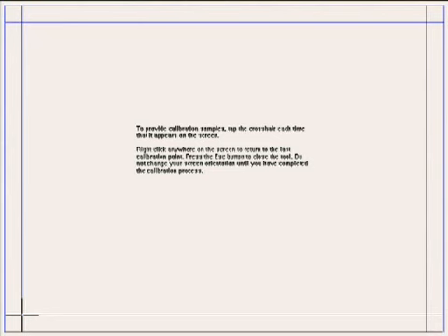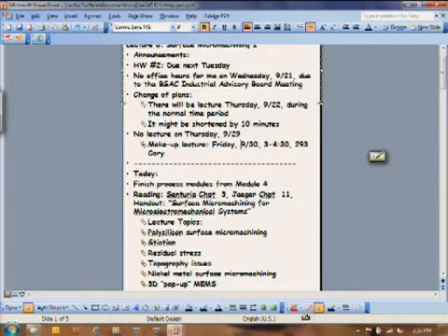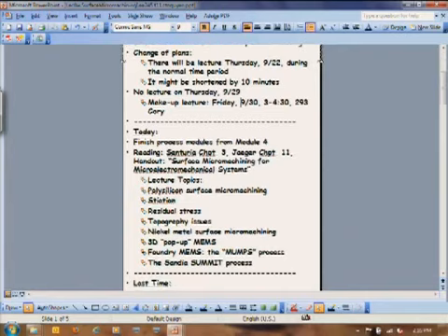Okay, so we'll talk about surface micromachining in general, just the whole process flow, polysilicon surface micromachining. Then we'll talk about all sorts of issues that you have with the process. We'll touch upon these briefly here because we'll go back and cover them in a lot more detail later on in the class. And finally, we'll end up with some almost foundry-like processes that you might have access to, where you can start playing around with MEMS should you have the ability to do that, say, from your research.